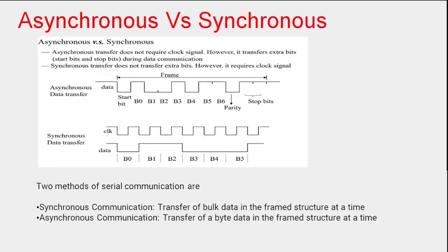If you look at the timing diagram of the UART, you could see the start bit first, which is 0, and the stop bit will have 2 ones. Usually the pin is high when data is not being transmitted. When the pin goes low, it means data is going to be transmitted at the start bit.